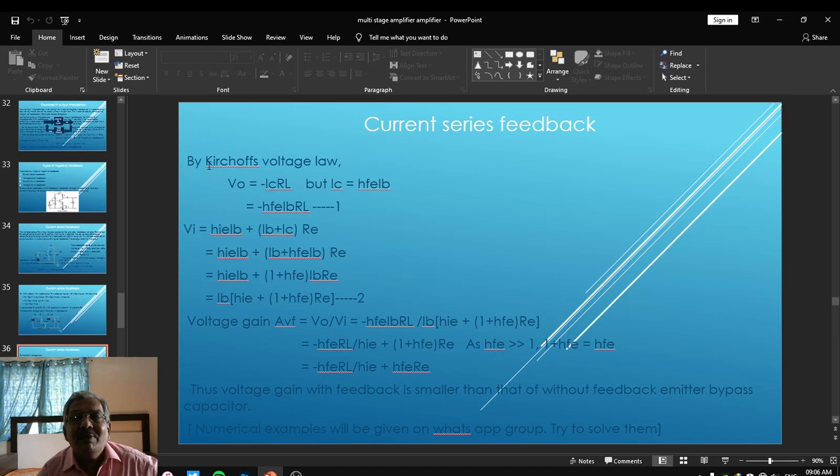Friends, by applying Kirchhoff's voltage law to that particular circuitry, we can get Vo is equal to minus Ic RL, and Ic is equal to hfe Ib, which you already know. hfe is here beta, remember beta is equal to Ic upon Ib. Therefore, we can write Ic is equal to hfe Ib. h parameters, friends, we have considered in last year.